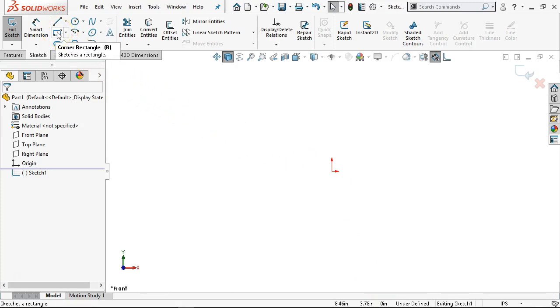All right, so I'm going to go up to the upper left, which is the sketching tools. In the first box, we're going to have lines, circles. We're not going to deal so much with splines until we get to surface profiles. And ellipses, going clockwise, the sketch fillets, the polygon, the slot, our rectangle is where we're going to start. And then in the middle is the three types of arcs. Anywhere you see the arrow, you're going to be able to pull down and make another selection. A center point, tangent, and three-point arc. Each one of those has a different rule that you have to follow to generate that geometry.